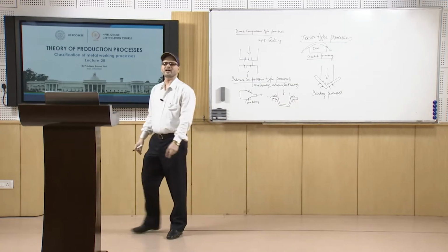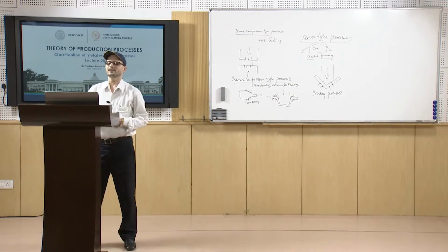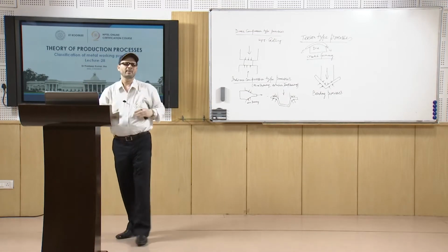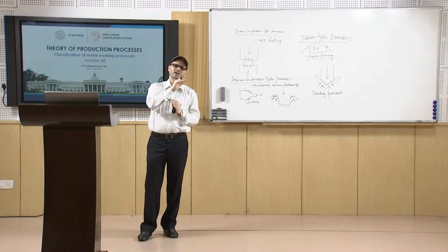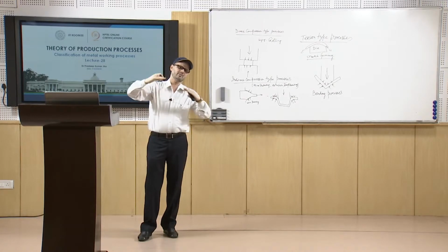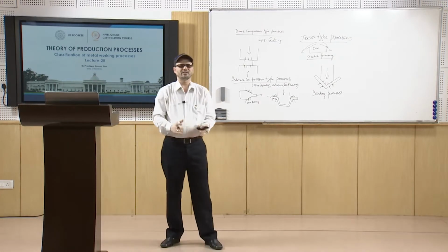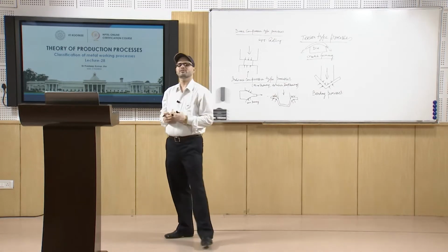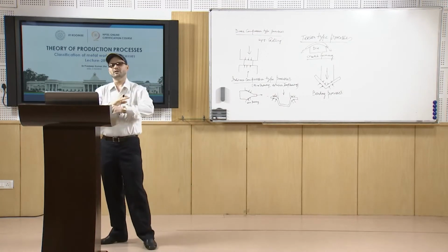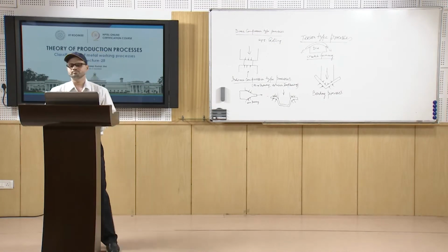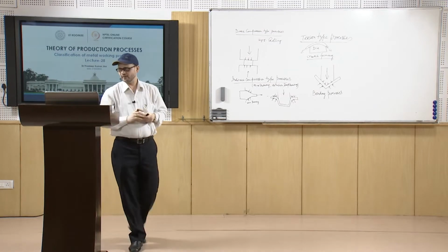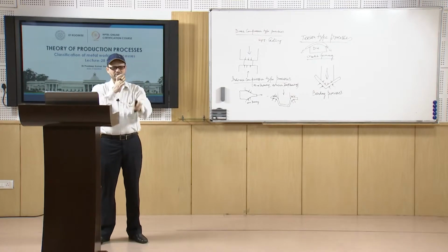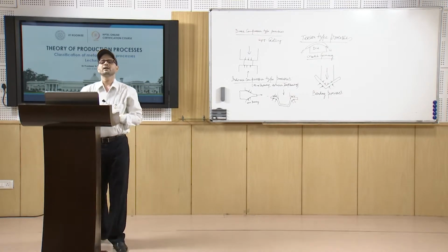Then next is the shearing process. Now in the case of the shearing process, what we do is you have the shearing action taking place. Normally you have a plate which is to be sheared, then you have a blade from the top and from the bottom, and because of the action of shear forces the plate is cut. So it will rupture the metal in the plane of shear. So that way the material will be ruptured and the shearing action takes place.